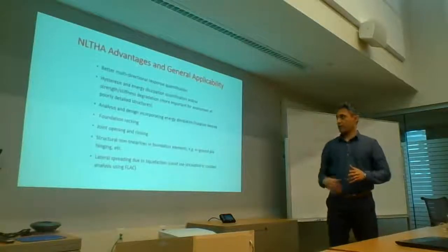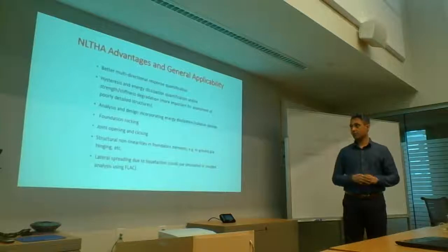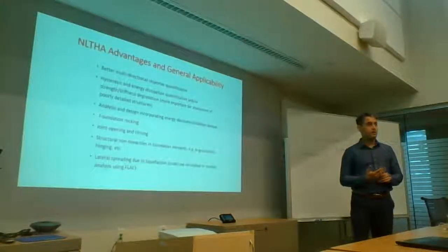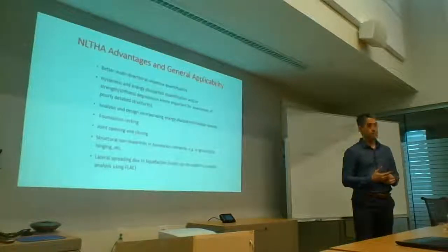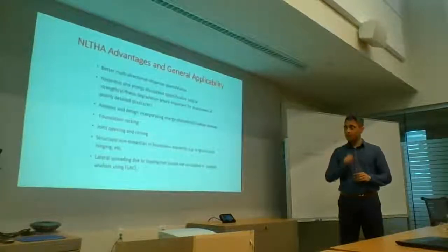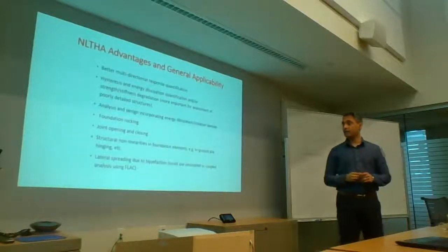You can quantify your hysteretic and energy dissipation. You can look at your strength and stiffness degradation, which is very important, especially for poorly detailed structures. So when you're looking at structures that need to be retrofitted, it becomes all the more important that we get a handle on it.